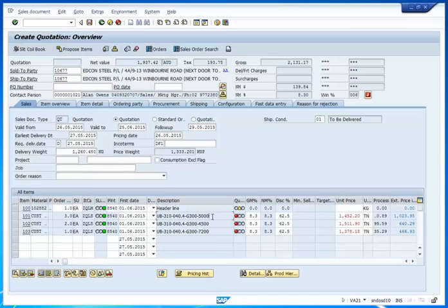So you can see the first line there is a 5 metre length, a 4.5 metre length, and a 7.2 metre length, and those are the quantities we basically entered into that configuration screen. The exact details of the type of cuts and the number of holes isn't captured here, but considering we did capture it through the processing model, it will flow through to the production orders that the operators will use to cut and supply this job.